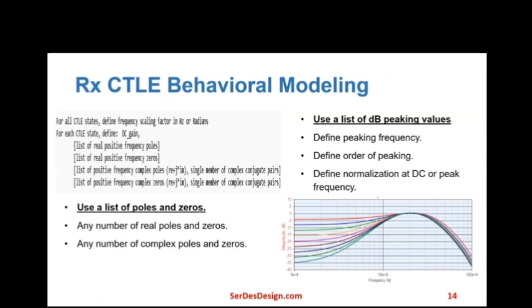This figure shows 9 state CTLEs with all peaking at 20 gigahertz. When the CTLE is specified, it can be defined as inclusive of the IBIS characteristic or exclusive of it. When it includes the IBIS portion, then the model automatically de-embeds the IBIS portion from the behavioral model to obtain the characteristics for use in the AMI portion.